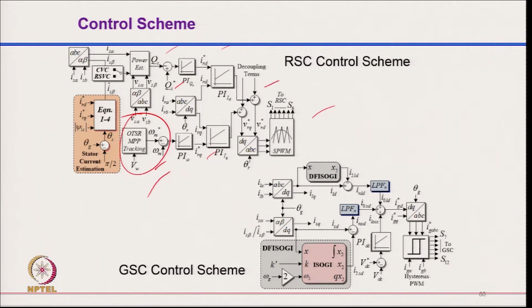And then you have a voltage control. Normally we use 1.8 kilohertz switching frequency for the rotor side converter. So, we have a voltage control after getting this. This vector control quantity of rotor voltage we convert using the slip angle into the 3 phase, and then we have the rotor side converter control, and this is your grid side converter control.